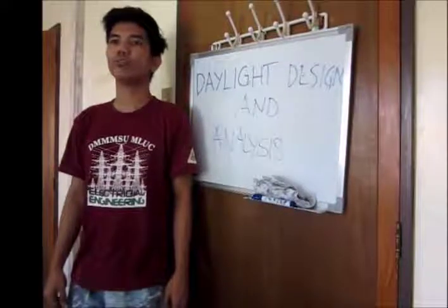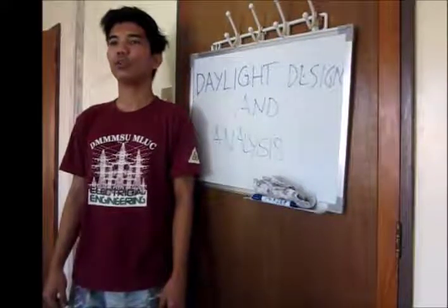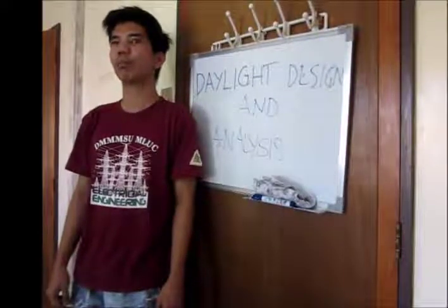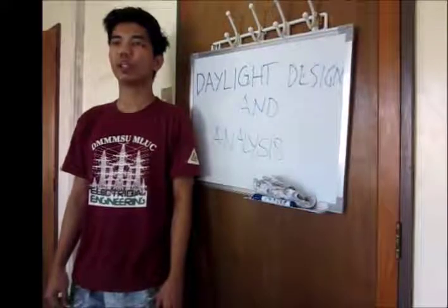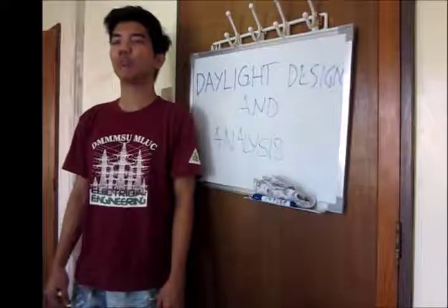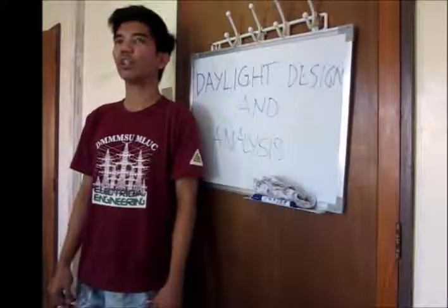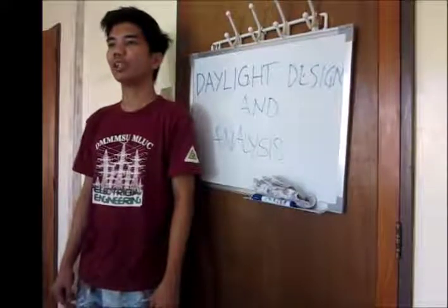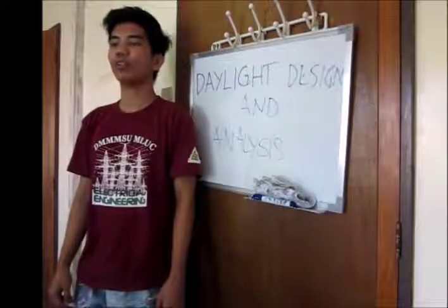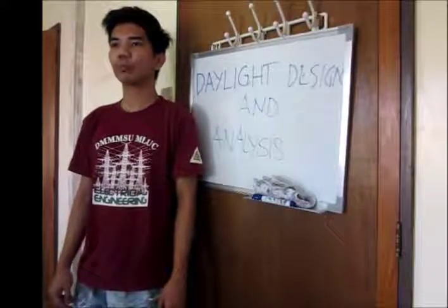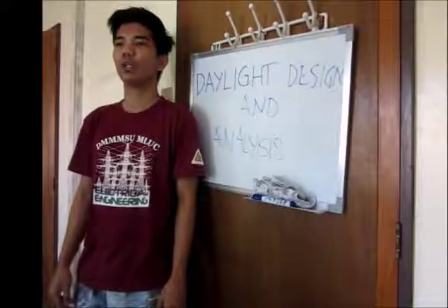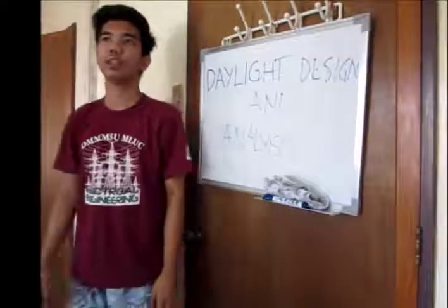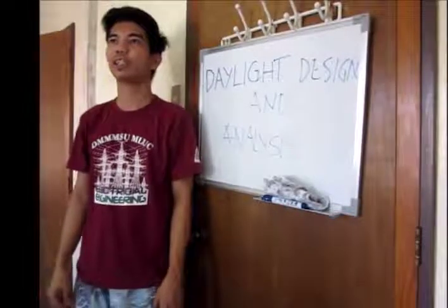Daylighting is the controlled admission of natural light into a space through windows, to reduce or eliminate electric lighting by providing a direct link to the dynamic and perpetually evolving patterns of outdoor illumination. Daylighting helps create a visually stimulating and productive environment for building occupants while reducing as much as 1/3 of total building energy costs. There are two distinct sources of light, the sunlight and the skylight.